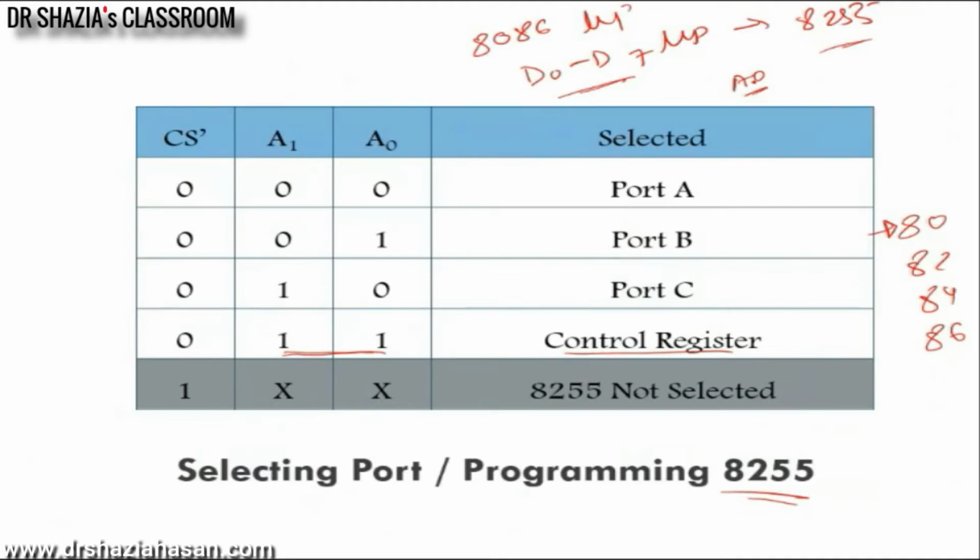How have you connected your memory chip? The same way we are going to connect here. Here also I have two memory banks, an even bank and an odd bank. The even bank will be enabled with A0 and the odd bank will be enabled with BHE bar. When A0 is 0, your even bank gets selected, and you have connected D0 to D7 of the microprocessor to 8255.